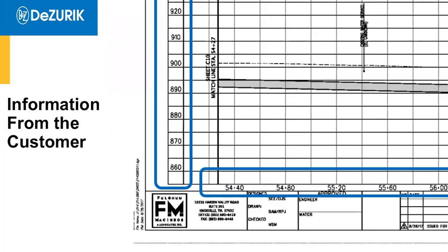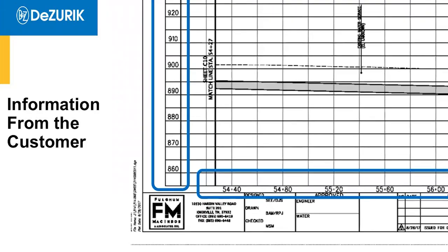So the surveyors and whatever else, they just like to talk in terms of hundreds of feet. So they say 5,400 feet, but then they add the plus 40 for the individual count of feet. So you'll see that sometimes it just means 5,440 feet.